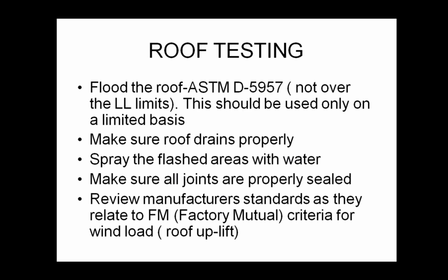And that test makes sure all the drainage works properly where it's supposed to, that the areas that have flashing get sprayed with water and there's no seepage behind it, and all the joints are sealed so you don't get water infiltration coming down through there.